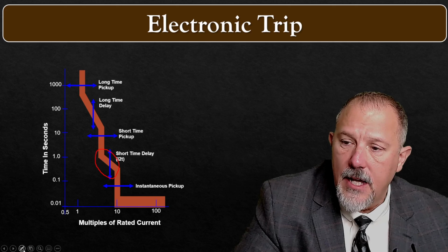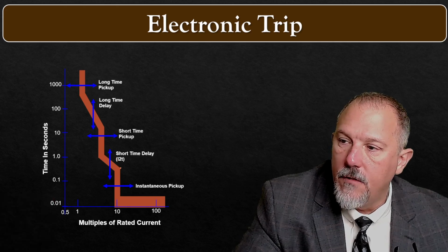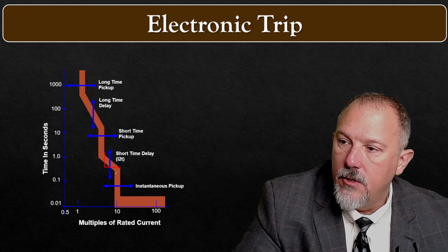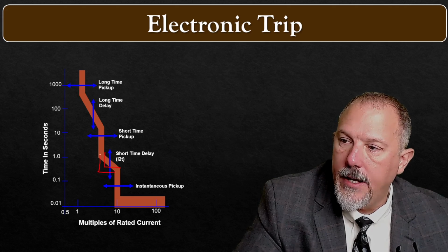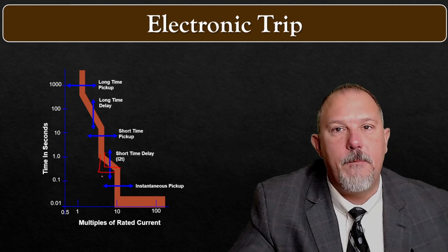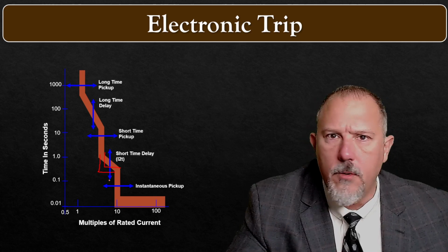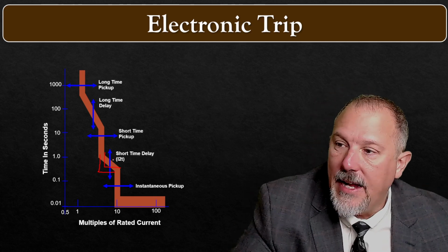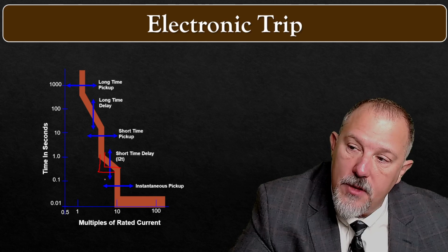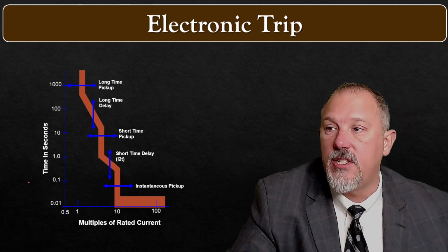In some cases, I can make that curve look like this, straight over and up, and provide a nice knee. Why would I do that? I might want to provide better protection in this region for, say, a motor, a transformer, whatever. I might want to shape this curve because of selective coordination, because I want to stay out of the way.